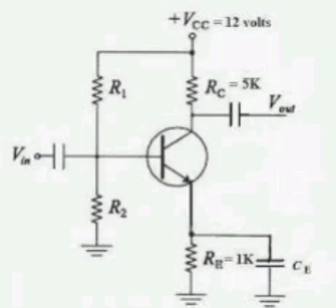In the series RL circuit, the switch is in position 1 long enough to establish steady state, and is switched to position 2 at t equals 0. Find the current i. At t equals 0 minus, the inductor reaches steady state, that is, it acts as a short circuit for the DC supply. So 50 volts is across 20 ohms. So IL of 0 minus equals 50 by 20 equals 2.5 amperes. IL of 0 plus equals 2.5 amperes for t greater than 0.